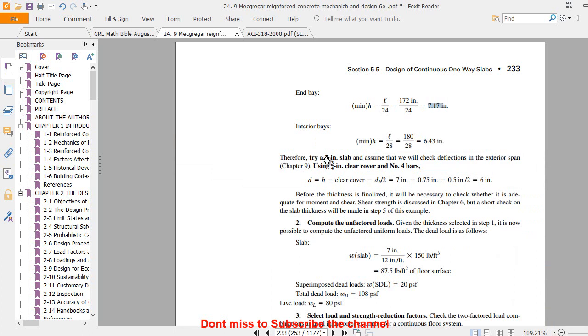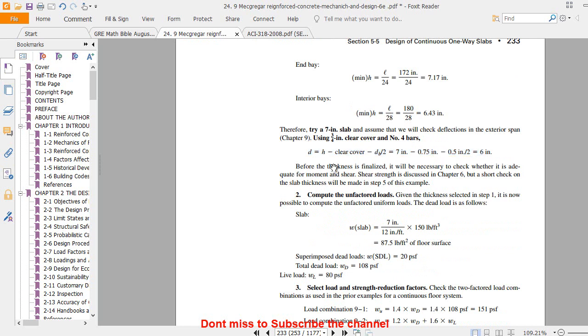So that's why we try a 7-inch slab system, assuming that the deflection in the exterior span, in chapter 9, inshallah we will discuss it in chapter 9, but leaving this at this moment, we are just fixing the slab thickness at 7 inches and using 3/4 inch clear cover. So this is the procedure to determine the effective depth, that is the overall depth minus clear cover minus db/2. Let's say we are using number 4 bar, so we are using 0.5 divided by 2, and with 3/4 inch clear cover, we got our effective depth as 6 inch.